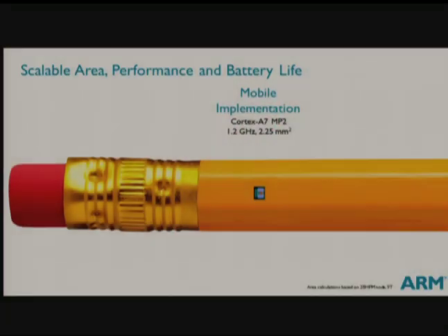I talked quite a little about the top right, servers: FIT rates, reliability, aging, wearing, all of that stuff. How do we scale this all the way down to the square millimeter tiny embedded systems? Let's have a look at some of the scaling challenges. Some scaling is easy. If you just take an ARM7 CPU core solution, 1.2 gig at around 2 and a bit square mil, so your cheap mid to low end phone, you can scale that for free into a wearable just by changing your synthesis targets. Don't push it to 1.2 gig, just aim for 500 meg, and you halve the size of the output. So you can get scalability by just backing off from what you're actually trying to do.